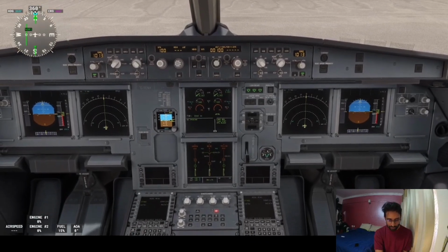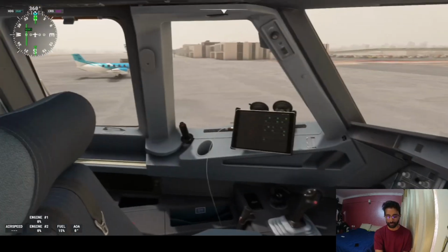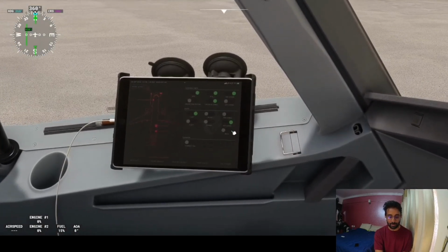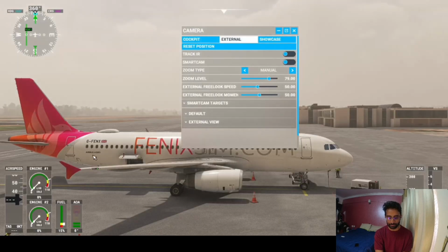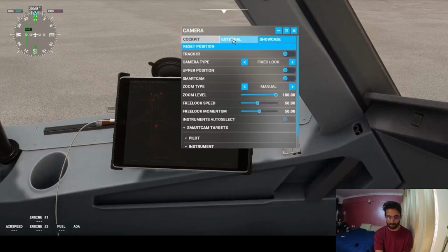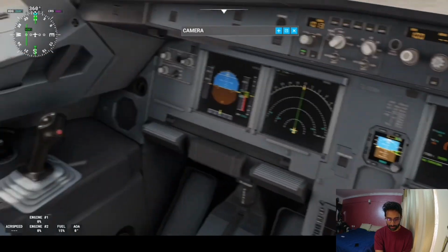When you turn it off, see, it depressurizes. Both hydraulic pressures are off. Got it? Now let's operate the cargo doors again, this time to close them. Now the cargo doors are closing. See, the front cargo door is closing, right? The bulk is also closed. You can see. Let's try one more.